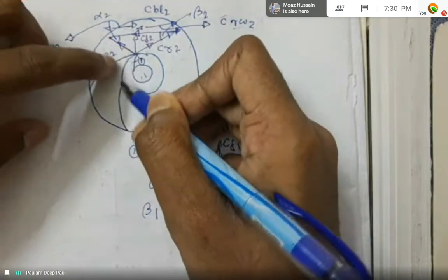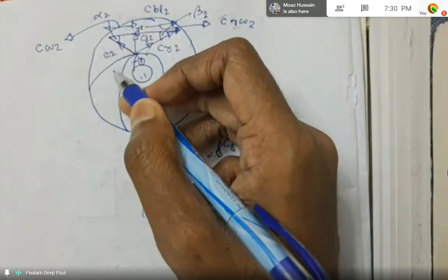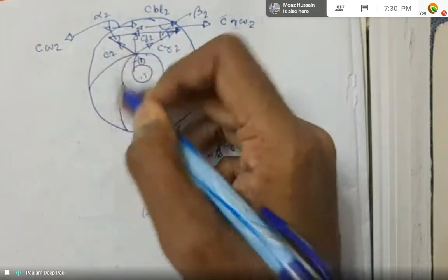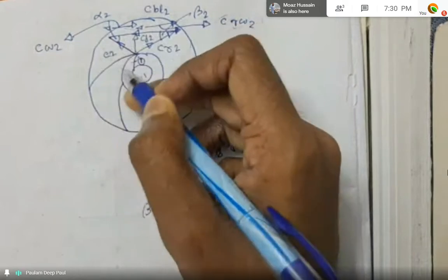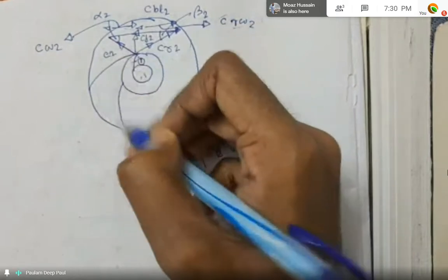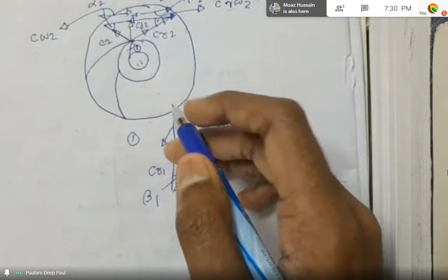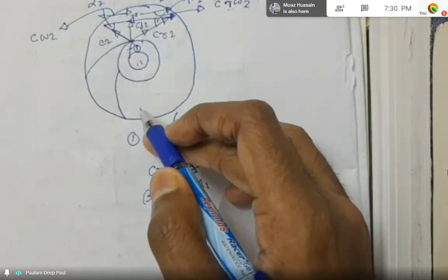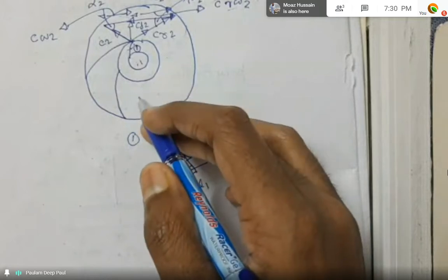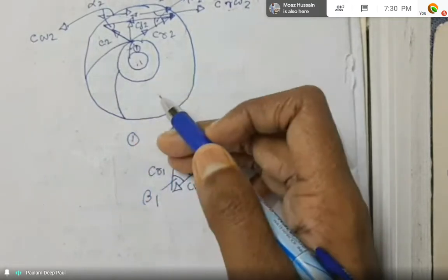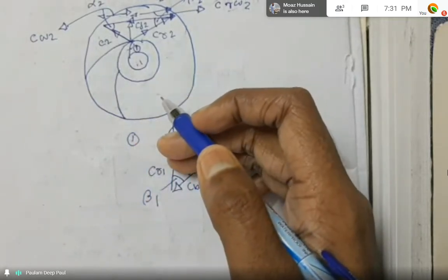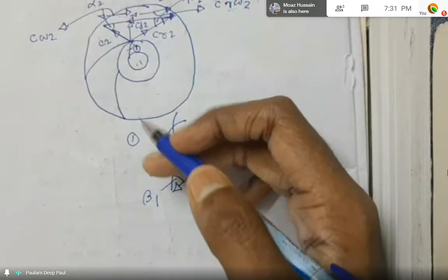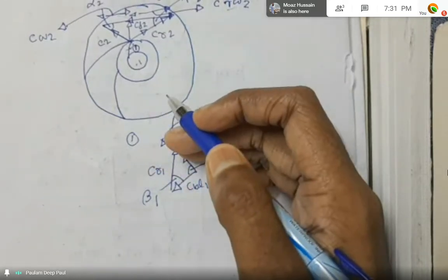As you can see, though it's in 2D, in 3D actually it goes on diverging, and in 2D also you can see the area is diverging from here to here. So the air now enters the diverging passage called the diffuser, where it is efficiently slowed down. The kinetic energy is converted into pressure energy, with the result that there is a further rise in static pressure.